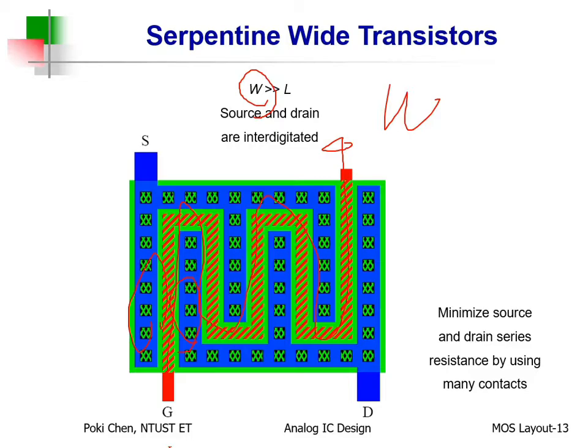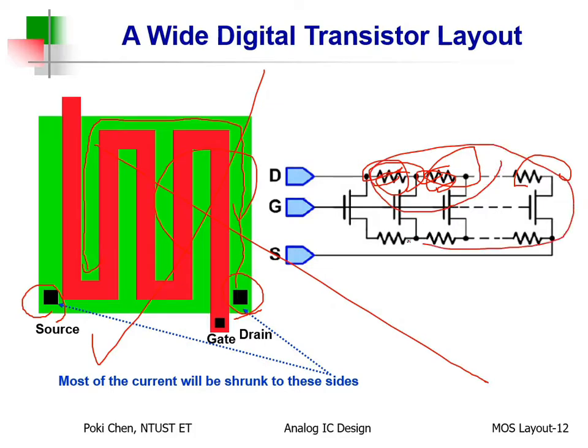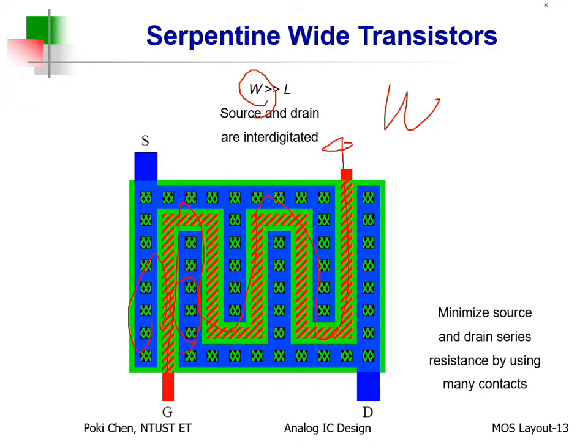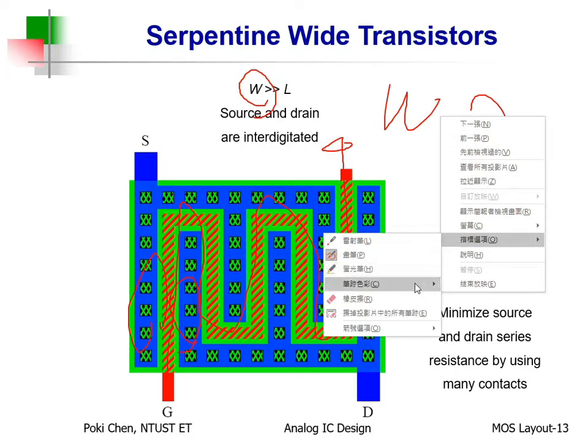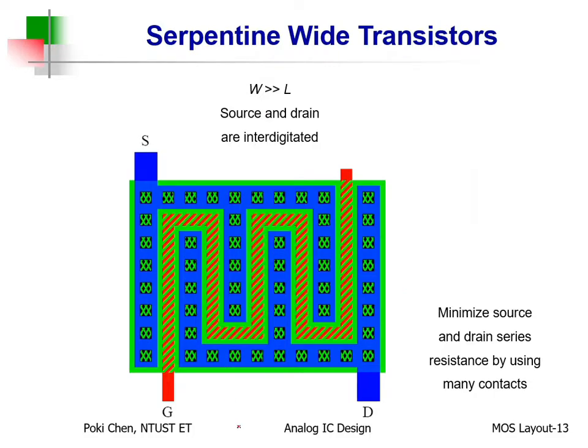Okay? This is not so bad, but it is not the best. Let's go forward. Because in this way, we try to solve the problem of huge resistance. But in reality, how much W it is, how much L it is is questionable. Okay? It means W and L both are not accurate. For example, why? Okay, from here to there, the length is the width of the polygate.